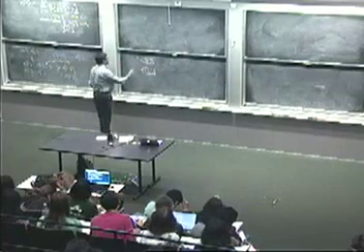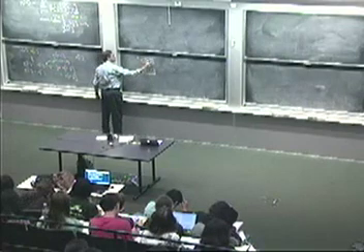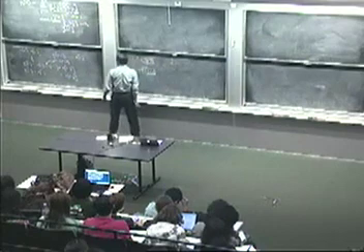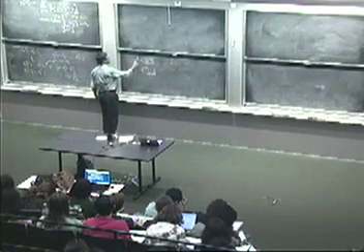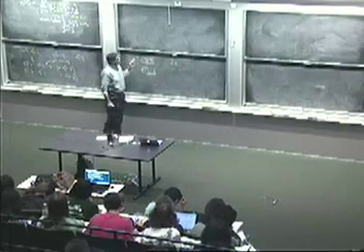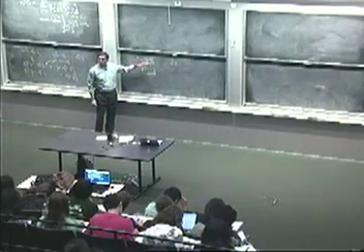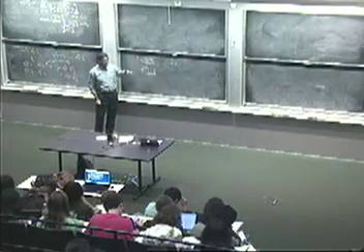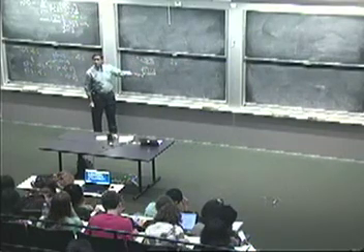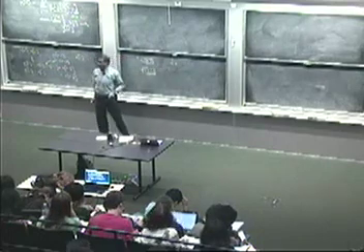So P0 is going to be xn plus xn minus 1 plus xn minus 2, so that gives you a 1. And what about P1? P1 is xn plus xn minus 2, so that gives you another 1. So if you're in the 0, 0 state and you get an input of 1, you're going to transition to 1, 0, and you're going to emit 1, 1.